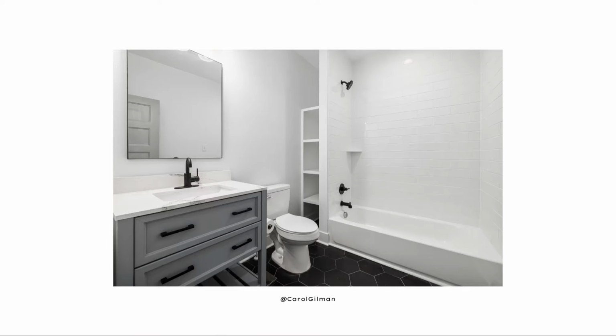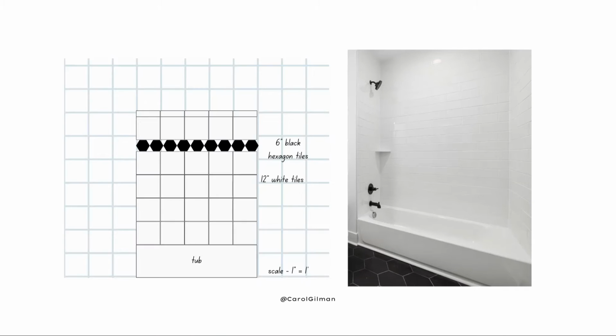What you could do is create a drawing to scale so that you could see the actual design of that tile layout. You could give that information to a tile installer or use it for yourself so you know how many tiles you'll need, what size of tiles you'll need, and exactly how that design is going to turn out. You may want to draw that where every 1 inch equals 1 foot, at a larger scale, because there are lots of little details and it's a smaller area.